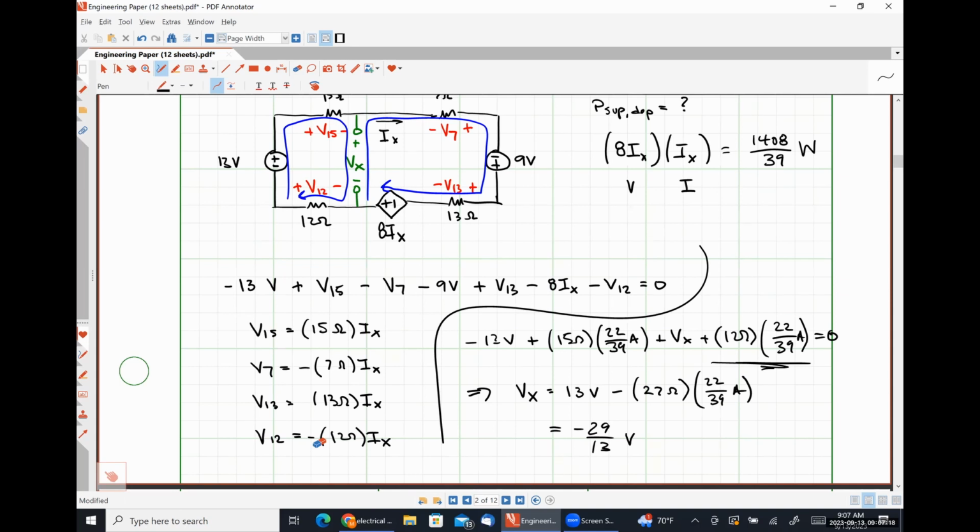For inductors, because it doesn't matter, we don't define it. For most capacitors, because it doesn't matter, we don't define it. Some capacitors, called electrolytic capacitors, are polarized, meaning that if you connect the voltage the wrong way, it will actually cause the capacitor to burst. And so on those, it is clearly defined what the positive polarity terminal is. For a diode, the polarity of the voltage across the diode matters a whole heck of a lot, so the negative polarity terminal is always identified with a silver stripe. For an LED, the long leg is positive, the short leg is negative, because the polarity matters. So effectively, if the polarity matters, there will be some sort of indication. If it doesn't, there won't be.